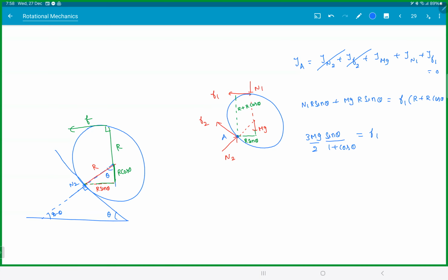That's what I'm saying. Calculating torque is the most important thing. You should take the distances properly. You are taking distances from point A. Extend the friction vector, drop the perpendicular. Have a look at this. It's a good one. This is how problems will be framed based on torque. So this is the new thing that you learned about today, torque. Remaining FBD, forces, all that stuff, you know.